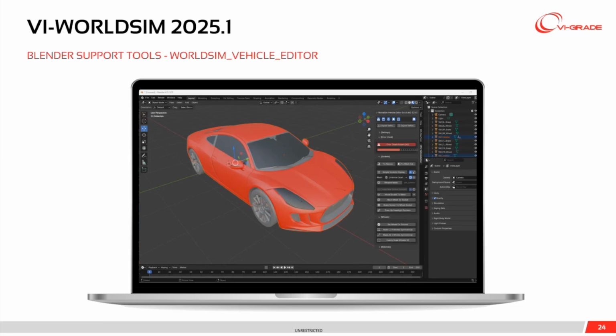The other tool that was available in the previous release was the vehicle import tool. One of the features with the vehicle import tool is you have to align your meshes with categories and organize it accordingly. Get the wheels in the right category, the exterior, the glass, the lights, the interior. But one of the things with the import tool that we noticed was that when you run the import tool, if you don't have your model aligned correctly, there was very little feedback on what was wrong with your model. So we actually have a vehicle checker tool now that will run through and do a quality check on your model prior to import, tell you what's wrong with it, and make suggestions on how to improve it so that you can optimize and streamline your import process.